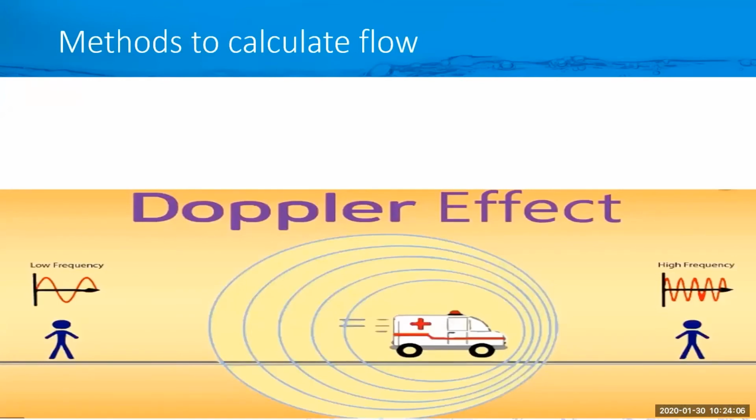With area velocity sensors like the ISCO in-pipe AV sensors, we use Doppler to read the velocity. We output a 500 kilohertz signal and read the frequency shift. What is a Doppler effect, as we're shown here with this ambulance, is that it transmits a sound, in our case a 500 kilohertz signal, and then it reads the frequency shift back to the sensor. As the sound or particles are moving towards the sensor, you're going to get a higher frequency, and as it moves away, it reads a lower frequency.